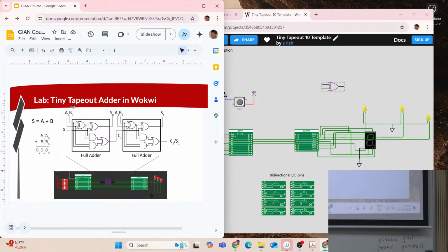So with two full adders like this is a 2-bit add, right? You've got your two input bits for your first source, your first addend, that's A0 and A1, and then B0 and B1 are your second input value, so each 2 bits.